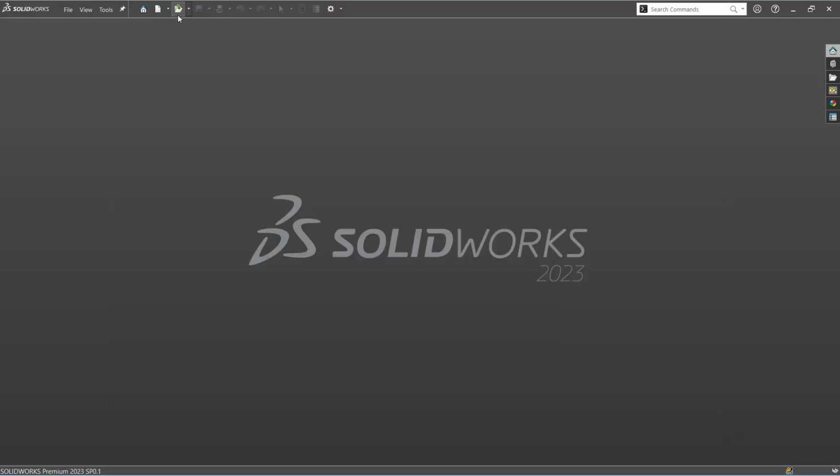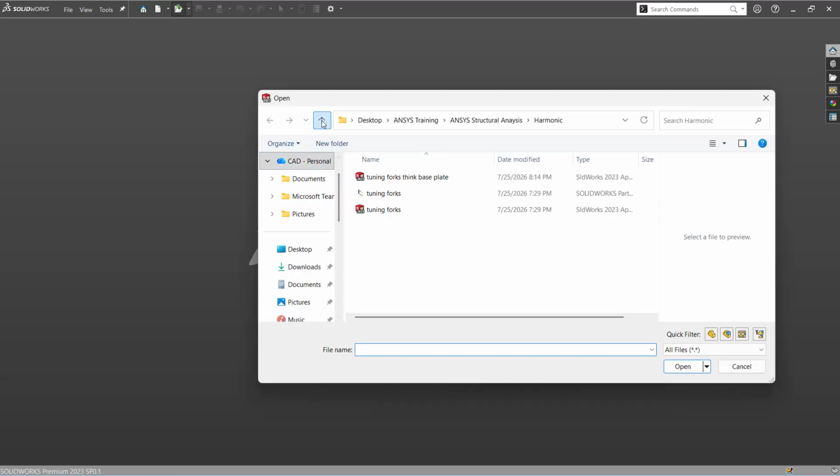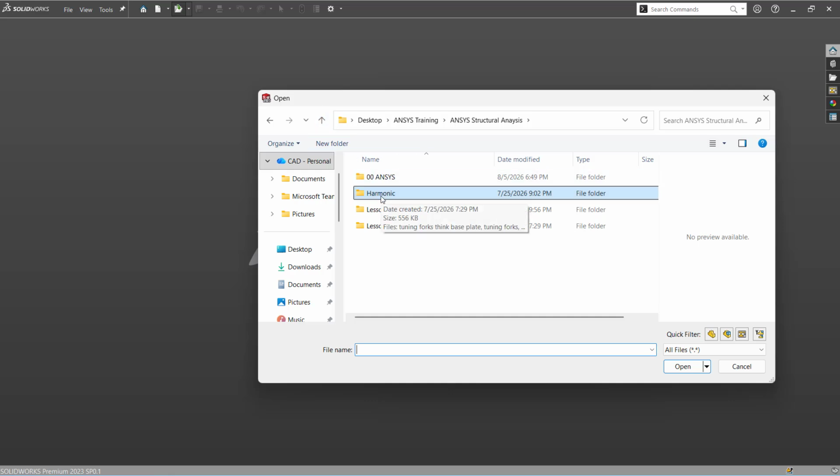Shall we try increasing that damping coefficient value? If we increase the damping, then definitely the displacement will decrease. Yes, that is it. But they don't want that, because practically they will keep damping at 2 to 3% only. For components, damping will be fixed based on the working condition, so if you change it, it is not going to impact them. So we need to improvise or make the model stiff and optimize it based on the need.